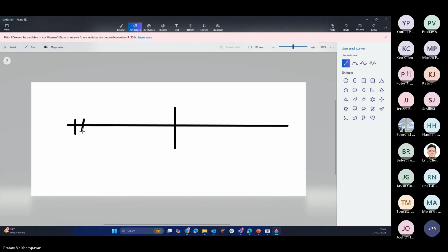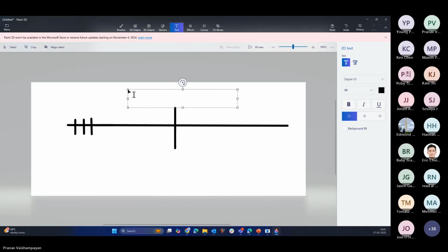Let's try it manually. Second and third and so on. So basically this will be 24.64 divided by 2. This distance, this half, and since our effective slab width is 0.616, we need to subtract: 24.64 divided by 2 minus 0.616 divided by 2.